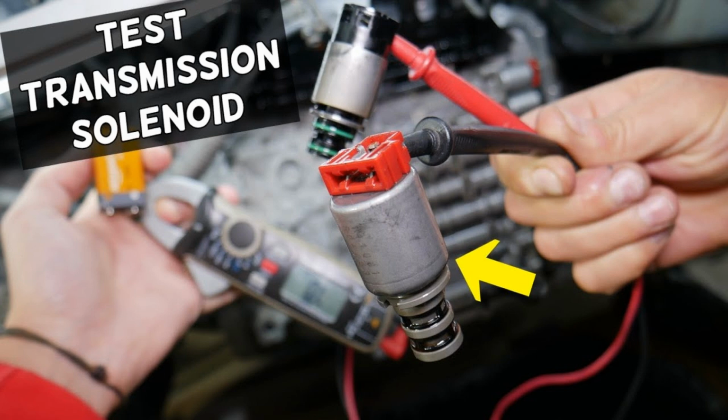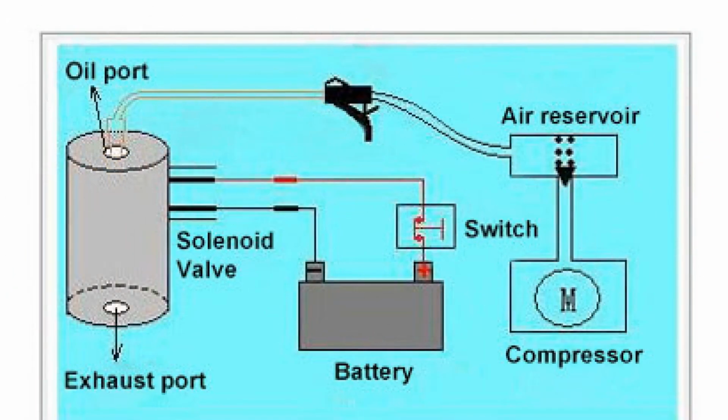The first to appear were solenoids that have a ball valve. They are called PWM. The development of modern control solenoids began with such devices. Somewhat later, another type appeared, which did not get much popularity and is now rare. Such solenoids are denoted as VBS. It is characterized by low sensitivity to supply pressure and works well at high lube oil pressure in the line. They are also often referred to as spool solenoids because they use a spool as the valve.